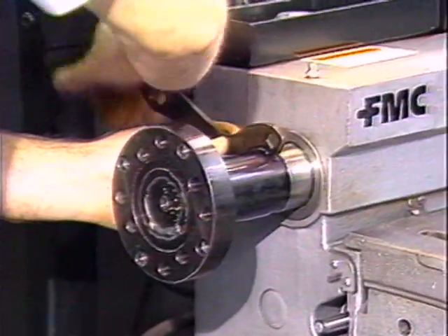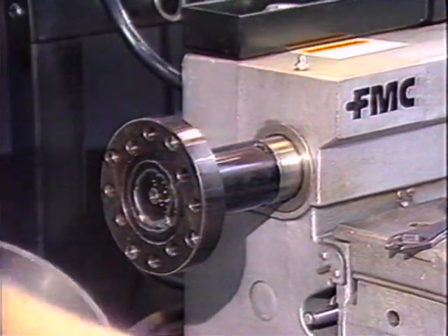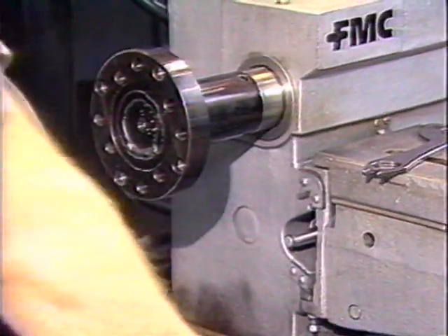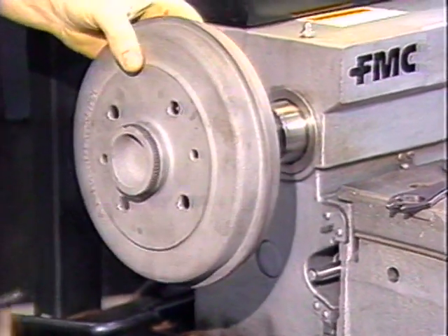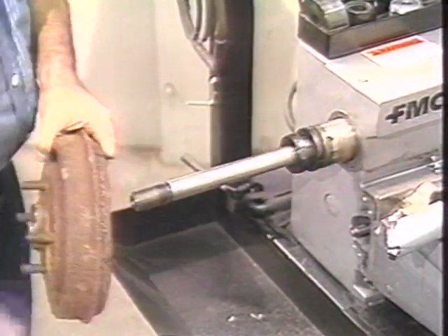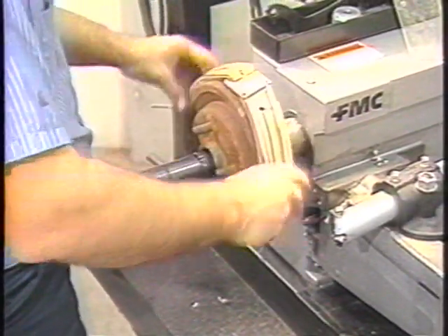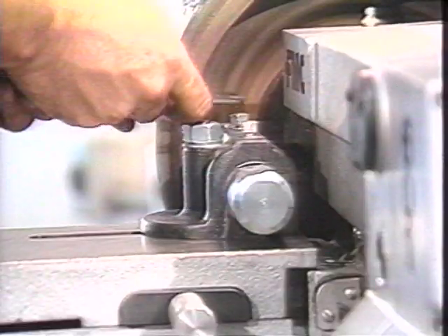Here is a special drum mounting adapter for a foreign car. The drum bolts to this adapter. If the drum has internal bearing races, you must use small cone-type adapters like these. Remember that the drum silencer band must be used before machining begins.